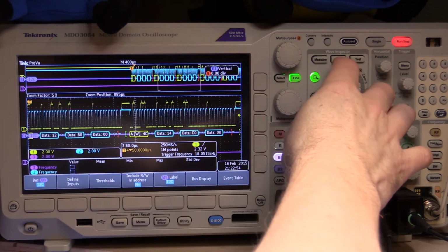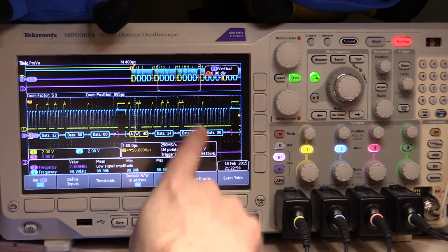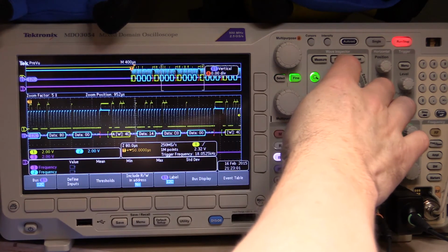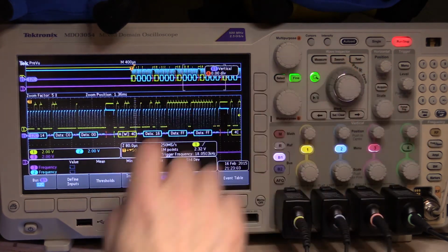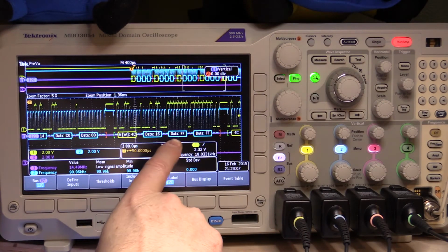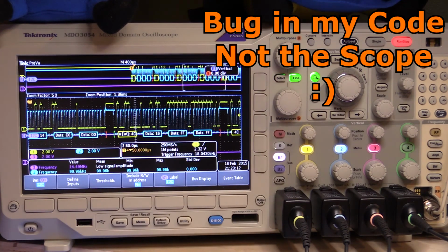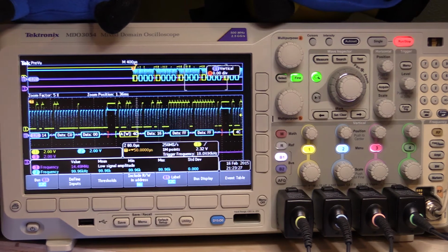And we got 4C again, and the next one, which is channel C, we got C000, and then we should have, if we're lucky, 4C again with channel D, and it's FFFF. So it looks like now that's working. Very minor bug, but of course, being able to throw it on a protocol decoder just using 2 wires sped up the diagnosis really.